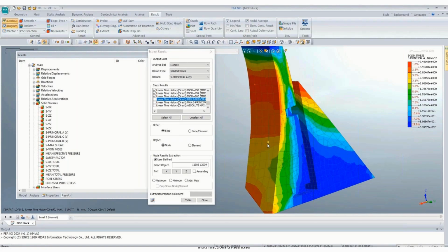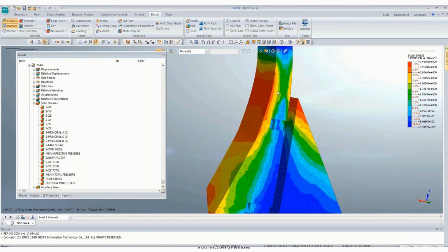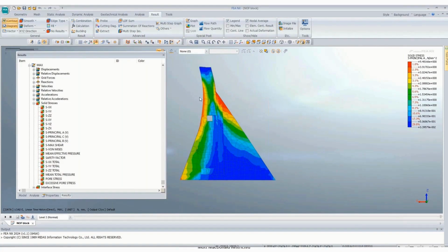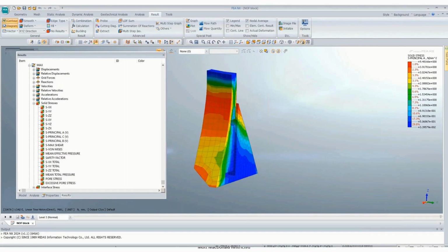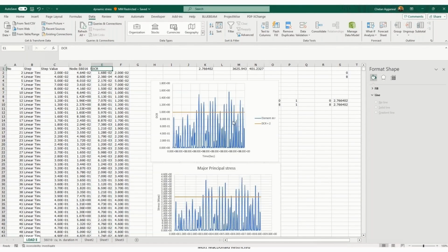Durations here for this node. Okay. So similarly for MC, we have to evaluate for similar criteria. That means we have to evaluate the reinforcement here, either reinforcement or we have to change its section here. Okay, we have to increase this section such that these values are less than, if I say provide M25 concrete. Okay, so these values should be less than this 2.77.